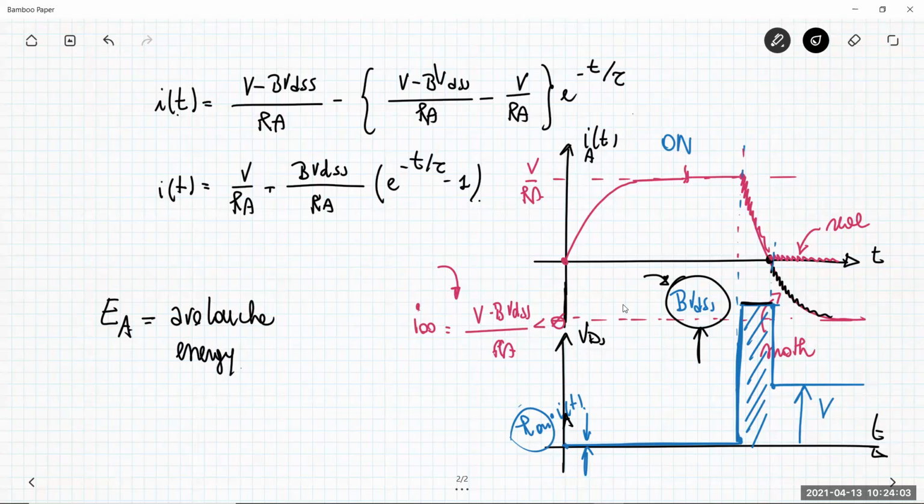This is the amount of energy that you can afford when you operate the device in the breakdown region before reaching permanent failures. So when you operate your MOSFET in the breakdown region, exactly at this voltage here, which is the maximum allowable when the MOSFET is off, and you are able to minimize the time interval in which you apply this operating region, minimizing the energy, then the situation is reversible.